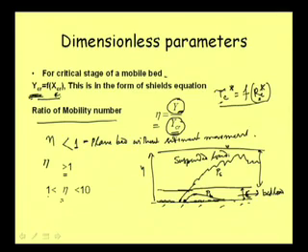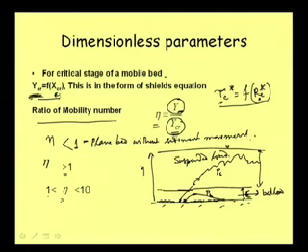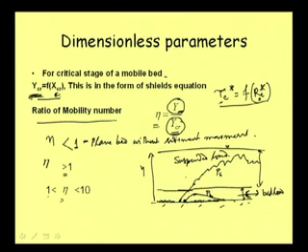So, in two-phase motion we get some particles moving just near the bed by jumping and rolling, and this sort of sediment component we call bed load. And then some other particles, with the increase of shear stress, with the increase of force, get into the main flow and get completely mixed up with the flow, and this we call suspended load. So, these two components we will get in two-phase motion.